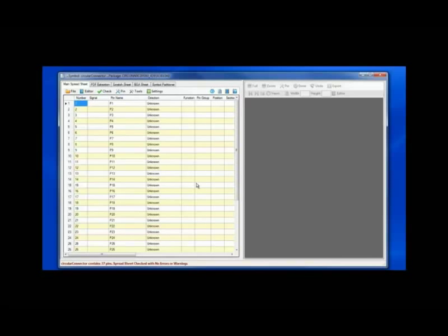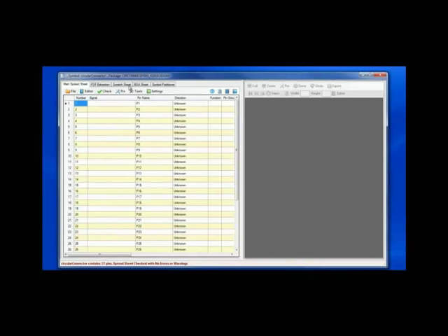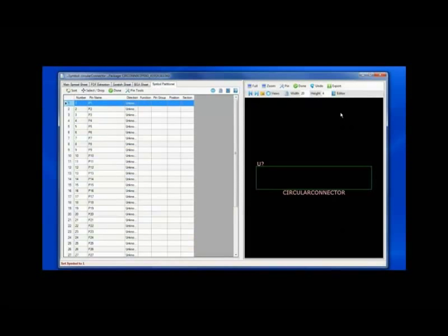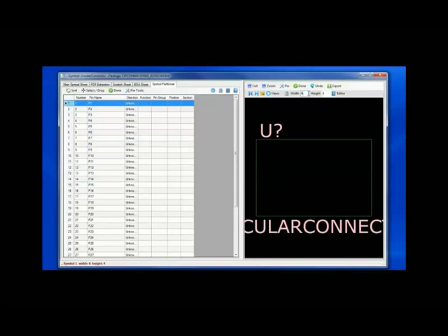I will now move to the partitioning of the symbol set, creating the schematic symbol model. Selecting the Symbol Partitioner tab, I will change the width to 6 units from the standard default of 20. I will select a group of pins.